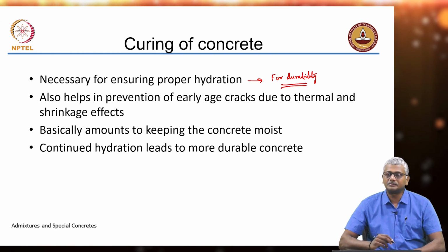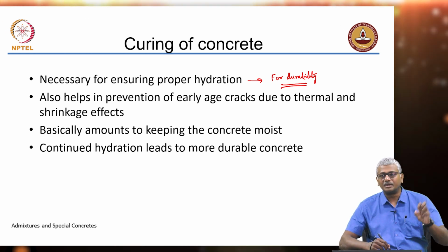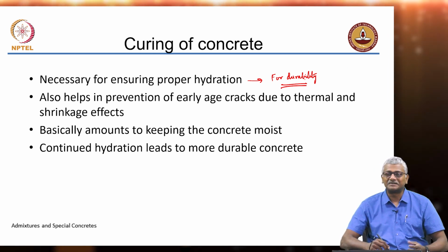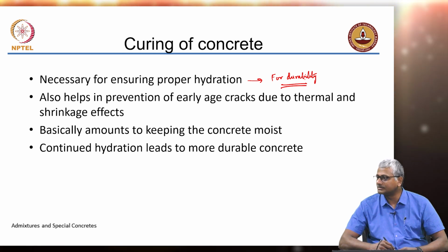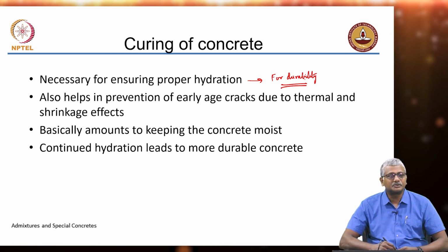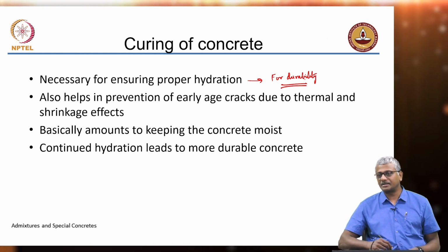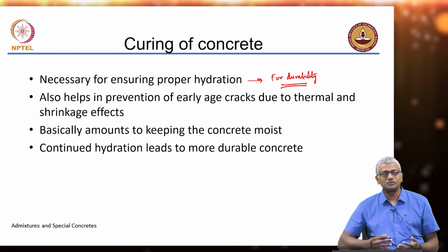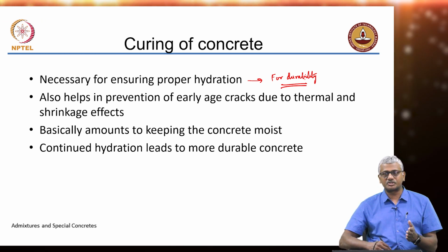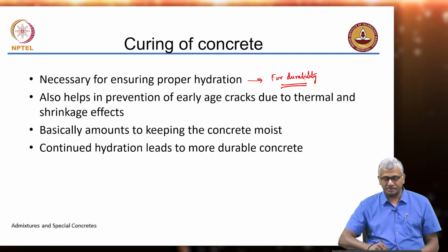Now, a lot of people seem to think that concrete is cured on the site to keep the concrete temperature low. It is not correct. You don't want to pour cold water on top of a hot concrete. It's a bad idea, right? So, that is a false idea in the minds of people at the site. They think that they keep temperature low by pouring water. That is not the idea. The idea is to ensure that a moisture source is available so that concrete does not dry out during the process of hydration.